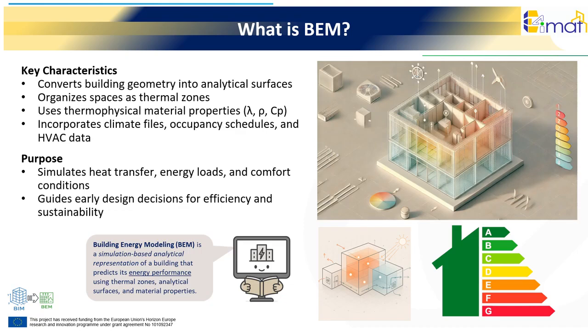BEM then combines all this geometric and zoning information with material properties, local climate data, and HVAC system characteristics. With these inputs, the model simulates heating and cooling loads, energy demand, equipment performance, and even indoor comfort metrics, such as operative temperature or thermal neutrality.